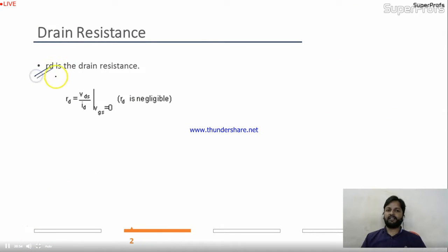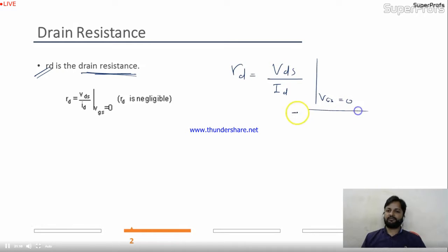And what is the RD? RD is the drain resistance only. Drain resistance means, what is the drain voltage? VDS. What is the drain current? ID. So, keeping VGS equal to 0. Please remember this: RD is the drain resistance. Definitely it will be VDS by ID but at VGS equal to 0. Is it okay to you?